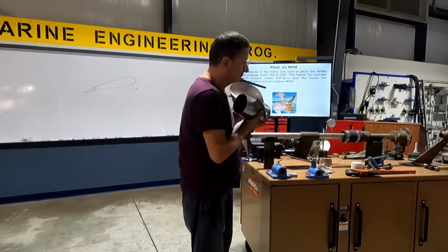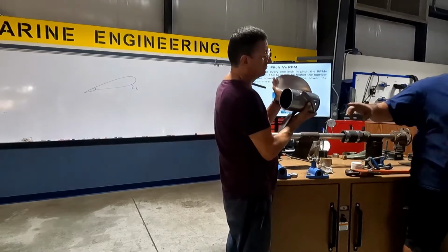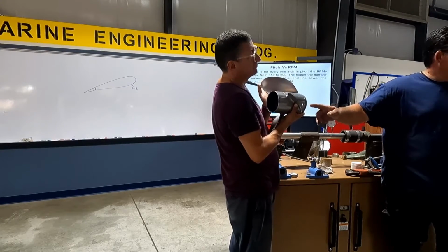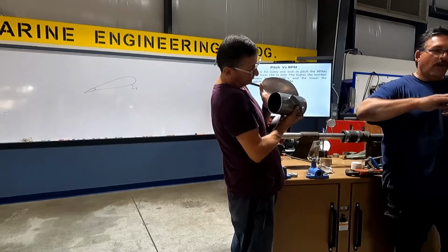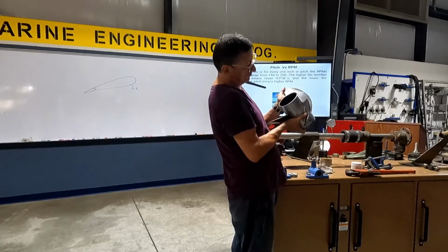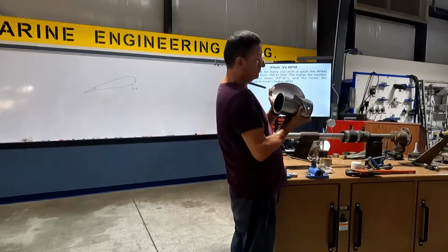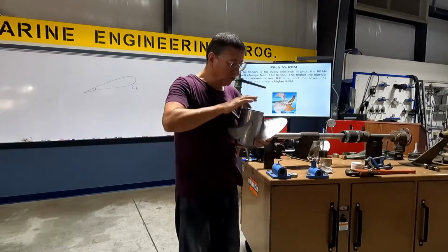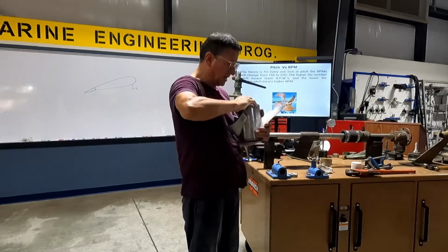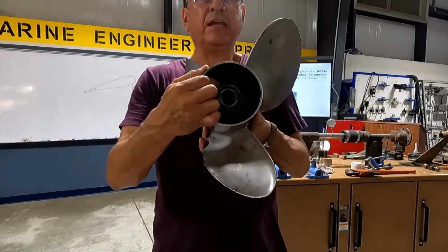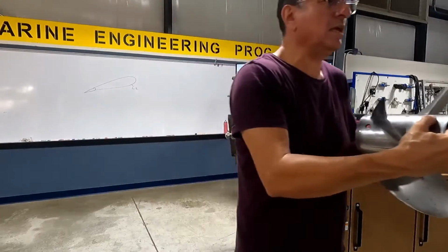It's all about performance. Evinrude has one that's really nice that actually has a little star screw that you can adjust, open a quarter, half, and we play with it. Like the guy that I know is just a Joe Schmo weekend guy, you don't care. This is nice, the nomenclature of this propeller. If you can see, they say it's 14 and a half in diameter and 18 in pitch.